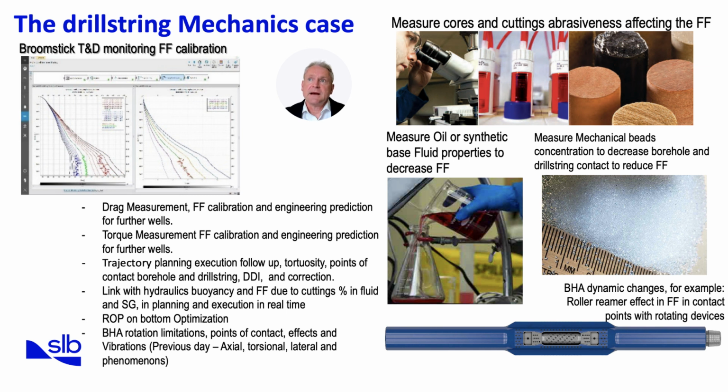To the right are chemicals used to reduce the friction factors, and at the bottom are tools such as the roller reamer that helps to reduce friction, vibration, and borehole rugosity. Altogether, these elements build a robust case for drill string mechanics monitoring. Next is a video on Encapso. This was a product in development with SLB fluids to provide improved lubricity in water-based mud systems.